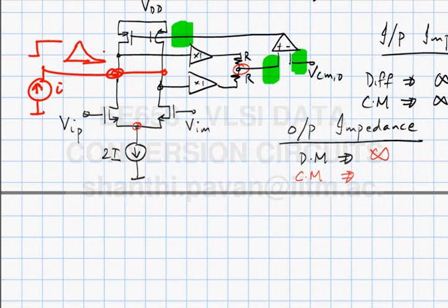If the op-amp is slow, what can you expect about this peak? So this peak is proportional to how long the op-amp takes to wake up. So if this op-amp here is very fast, then the op-amp wakes up very quickly, so it will just do that.